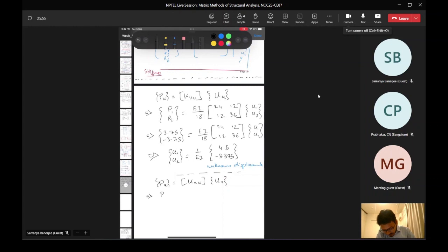So now we have P unknown as P3, P4, P5, P6. We have K UK as EI by 18, 0, 6, minus 12, minus 12, 12, 9, 0, 3, and 1 by EI into 4.5, minus 3.375.